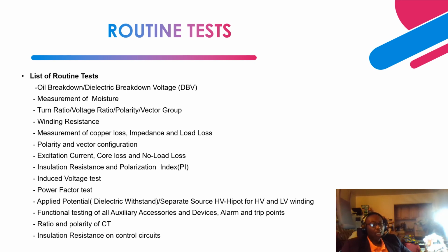During shipping from the factory after factory acceptance testing to the site where the transformer is going to be installed, the transformer can get damaged, or the active component can get shifted when the transformer, let's say, falls down. So the goal is to perform this impedance testing and compare it with the testing results that were obtained in the factory. And there should not be any change greater than plus or minus 7.5% for a new transformer.